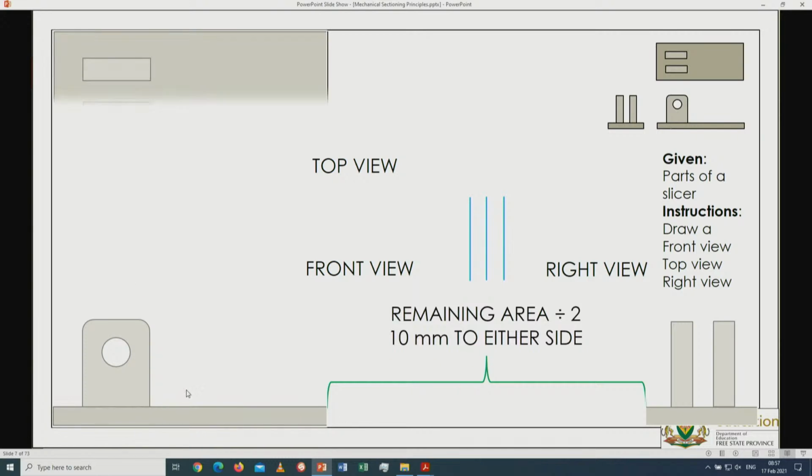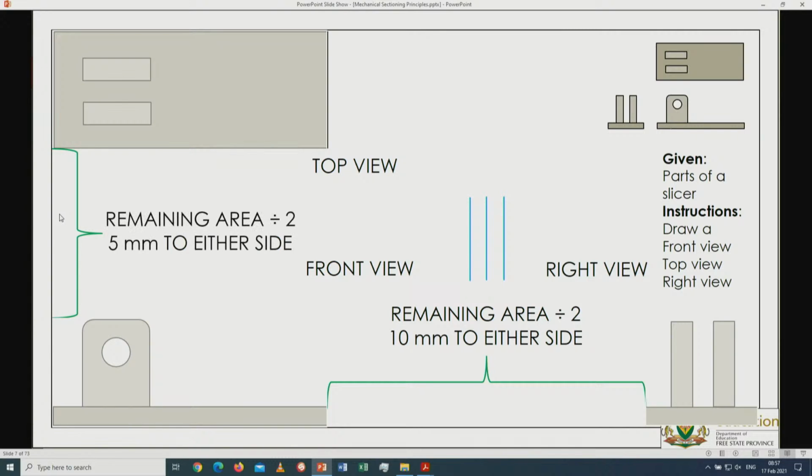All right. Then from there on, for the top view, this is the depth of the top view. How deep does it go, in other words? So we can also say it needs to be accommodated by this size. We take this distance from there to there and divide that distance by 2. And then, of course, we can say, right, let's go 5 up and 5 down to keep the drawings 5 millimeters apart from each other over here. So that's the middle point, and from there, 5 up and 5 down gives me 10 millimeters apart from each other.